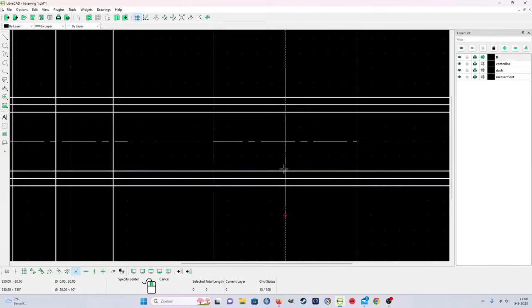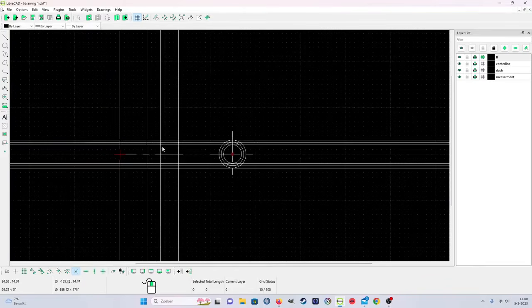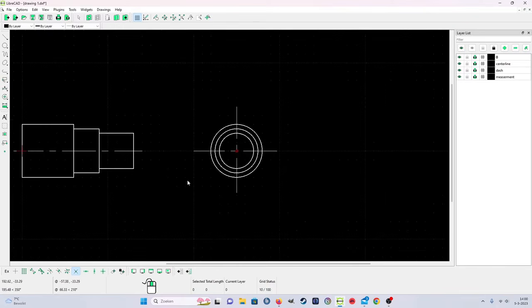You see, my yellow circle is going exactly to the next cross point. From here to here. Okay, and then the next one, very simple, from here to here. The next one, very simple, from here to here. So now I have an exact copy of the measurement of my shaft. Now I deselect the square, and I got the exact measurement copied to the right side view.